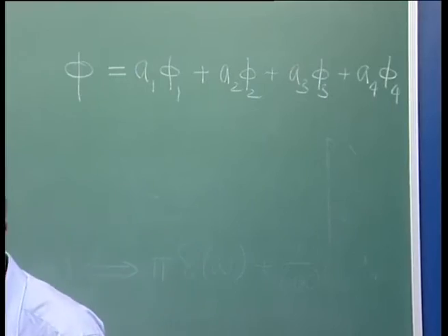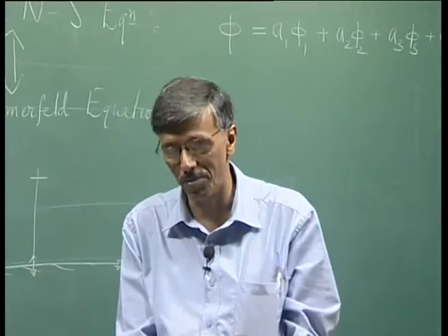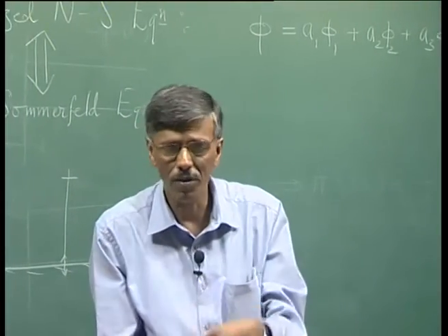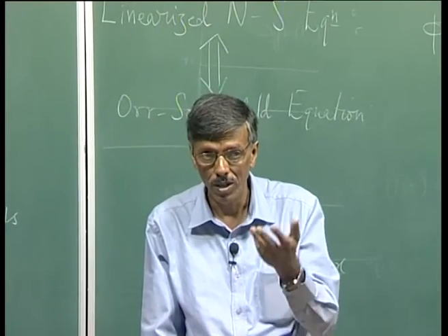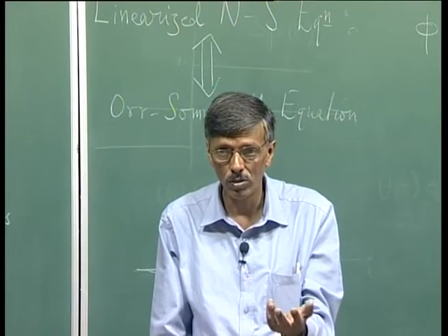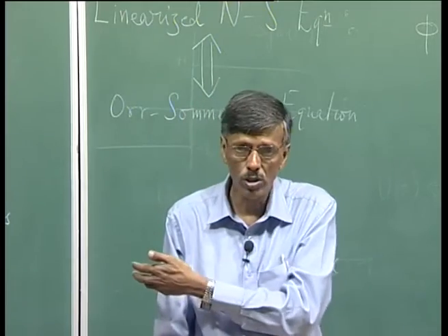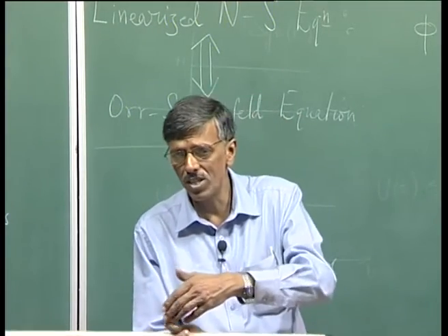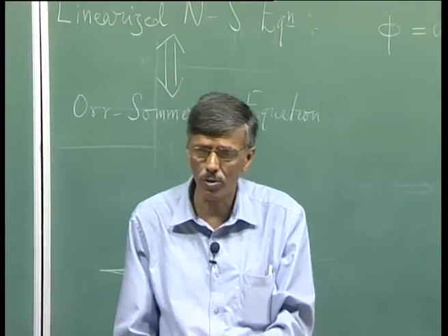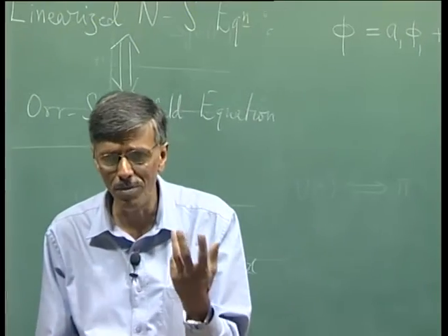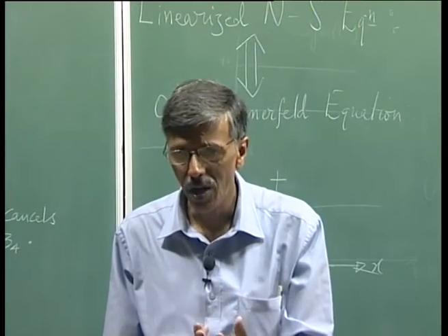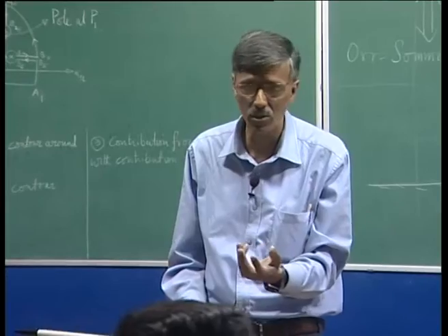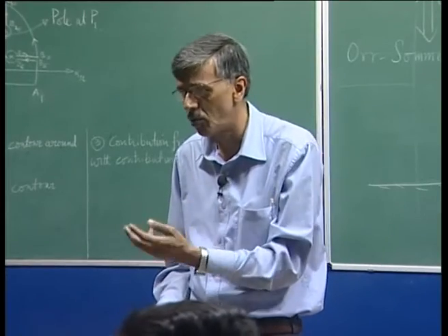Well, we only know them when we go outside the shear layer. Recall, that is how, in defining the initial condition for the compound matrix method, we evaluated those modes. You can substitute your condition of y going to infinity. What will happen? U of y will become 1, u double prime will become 0, and then we will have a constant coefficient 4th order ODE, and we get those 4 modes.